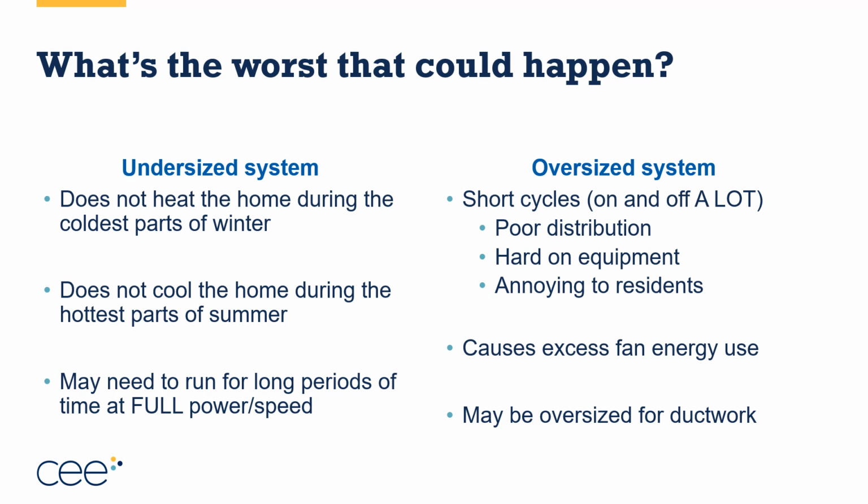Well, undersized systems, this is where there really could be a problem, but the good news, this is extremely rare. We'll get to why it's extremely rare in just a little bit. But why would it be important if you undersize your system? Well, if you undersize by 95% of the heating load or lower, you do run the risk of the system not being able to heat the home during the coldest parts of the winter. And nobody wants a brand new system installed that cannot heat the home. We also don't want it to not be able to cool the entire home during the hottest parts of the summer.